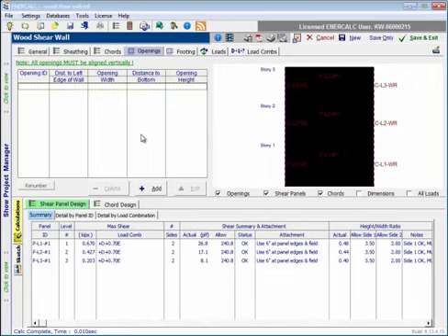And so what it does, therefore, is it divides one shear panel into two shear panels, one on either side of the penetrated portion, and any contribution to shear resistance from the portion that has the penetration in it is just completely neglected from the perspective of shear resistance for wind and seismic.